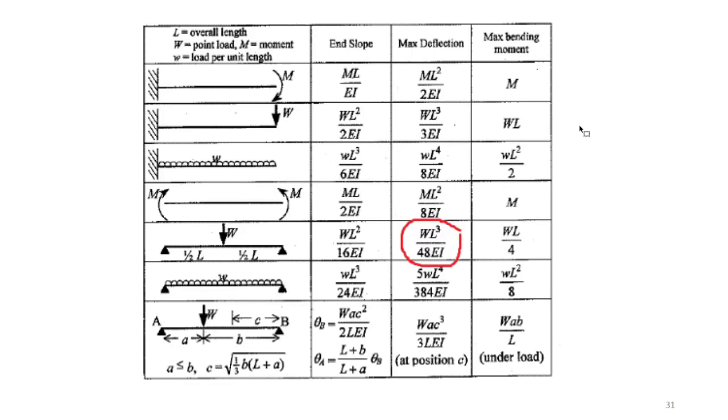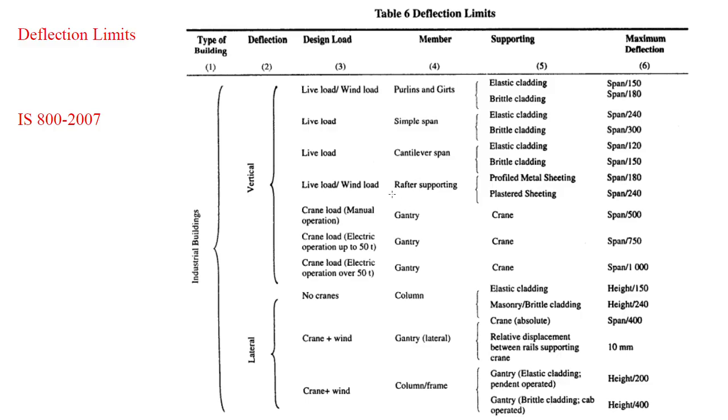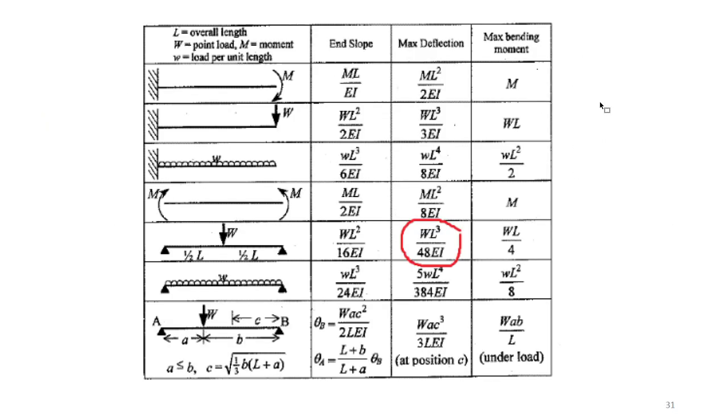Okay, the deflection which comes from the load should not be more than the maximum deflection allowed in the selected trial beam section. If this deflection is less than the maximum deflection limit, then the section is safe in deflection.